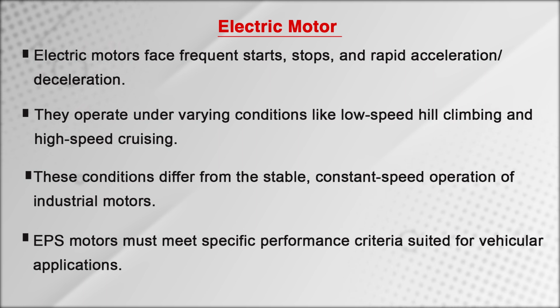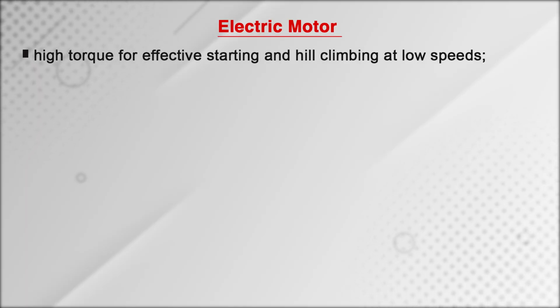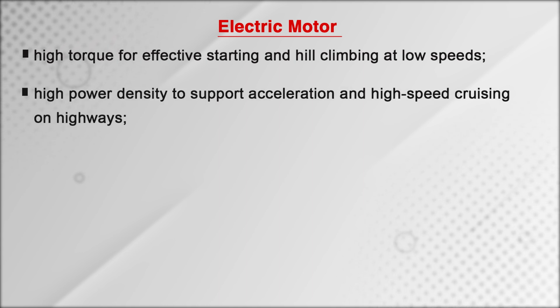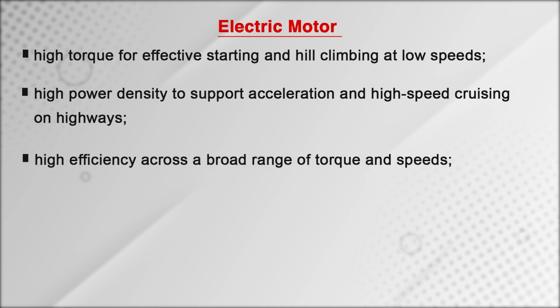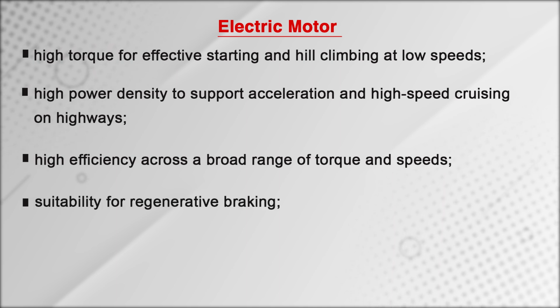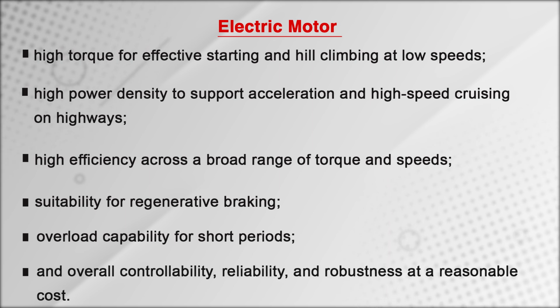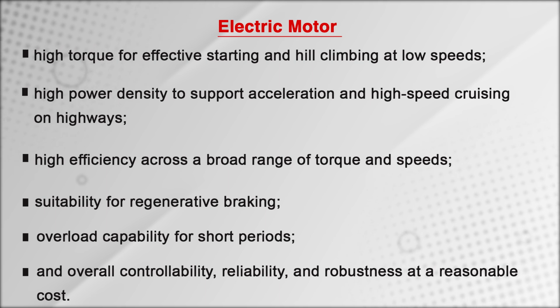So, electric motors used in electric propulsion systems must exhibit several key characteristics such as high torque for effective starting and hill climbing at low speeds, high power density to support acceleration and high speed cruising on highways, high efficiency across a broad range of torque and speed, suitability for regenerative braking, overload capability for short periods, and overall controllability, reliability and robustness, all at reasonable cost.